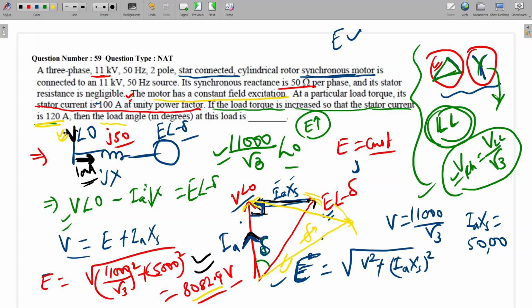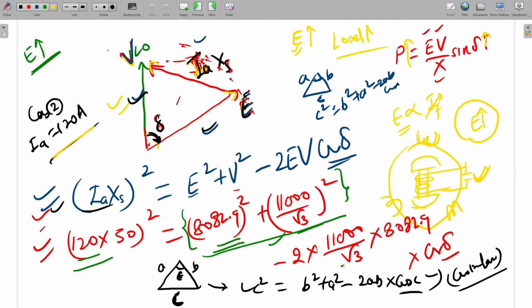So for the delta again, the power factor angle is not given. So whatever information is given, this is the only way we can calculate the delta with that given information. So we can't take unity power factor again in the second case. Power factor will not be unity, because see, this is the current direction. So current and I_A axis will be always perpendicular. So this will be the current, this is the I_A axis. So current will be somewhere here, and this will be lagging in nature.